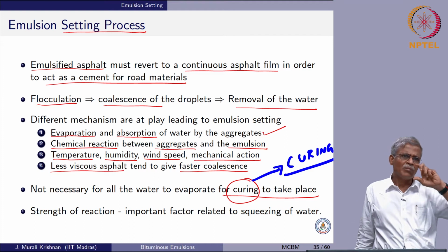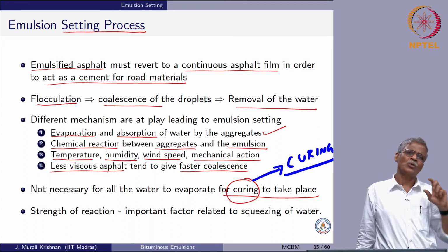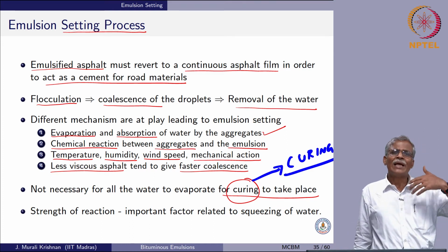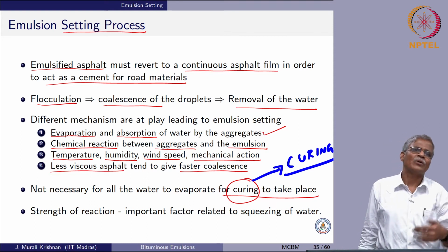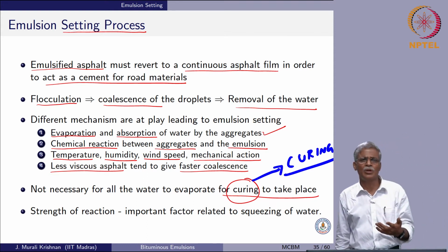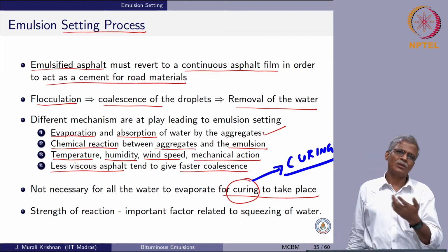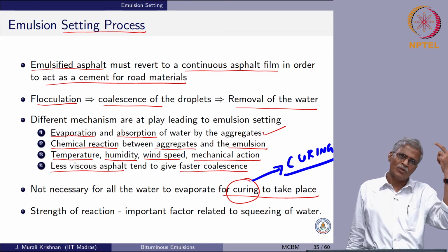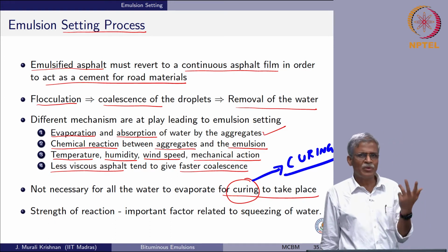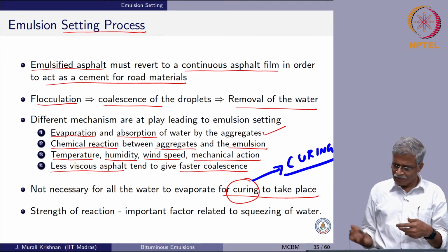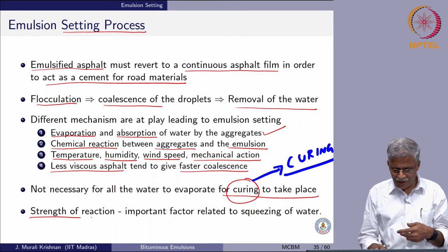For the bottom portion, which is the base course material, to gain its strength, let us say if you have assumed 200 MPa as the modulus value, to reach its actual strength it might take 3 to 4 months, and that is something we need to keep in mind when designing our pavement. And the strength of the reaction.